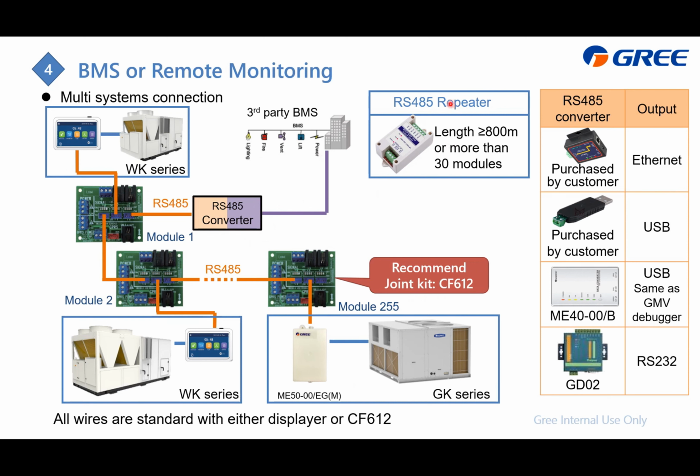And here I just recommend that if the length is more than 800 meters, or there are more than 30 modules, which is 30 of this one, we recommend to apply the RS-485 repeater to ensure the communication.